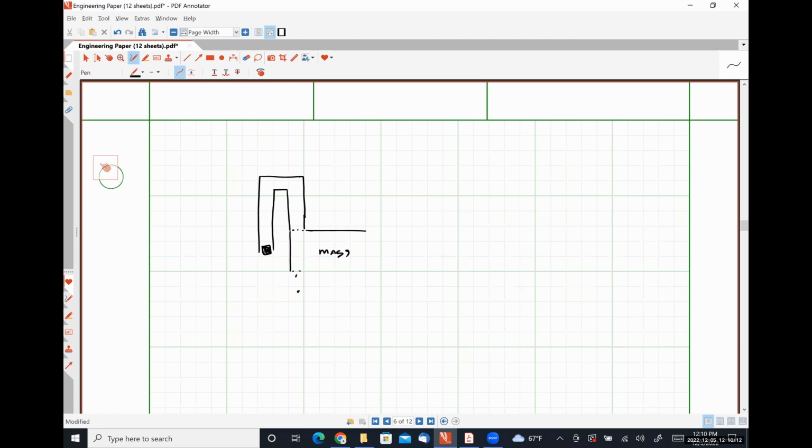So if we apply a force to our mass, what we're going to see is that this cantilever spring, which is anchored here, is going to deflect in this direction. And then this cantilever spring, which is anchored here, is also going to deflect in that direction. So we're going to have something that has a profile effectively like this. This point right here, which is this large thick connection, we say that it's stiff enough that it can't rotate or deflect itself. So that's what I mean by a guided spring in a MEMS device.